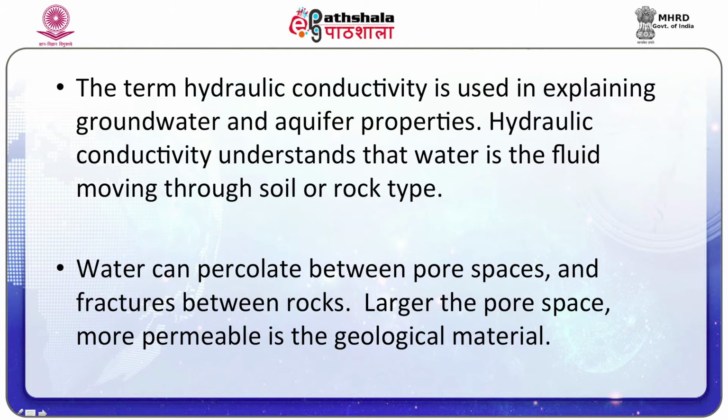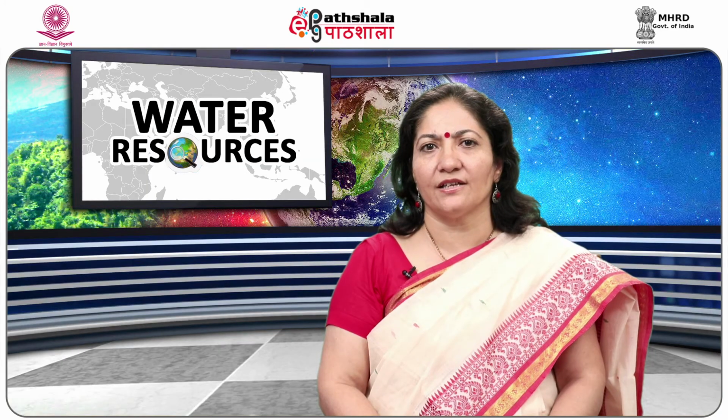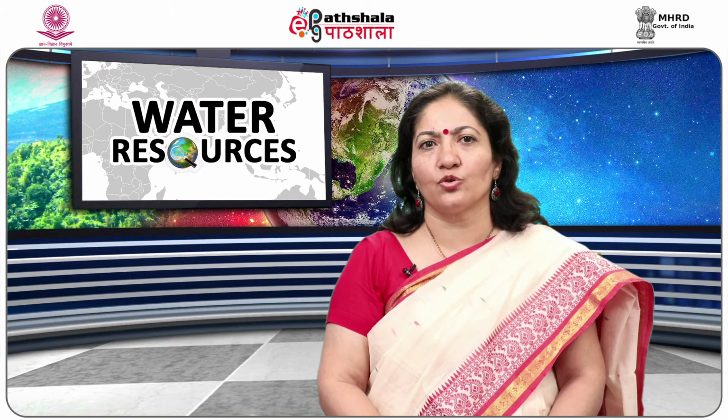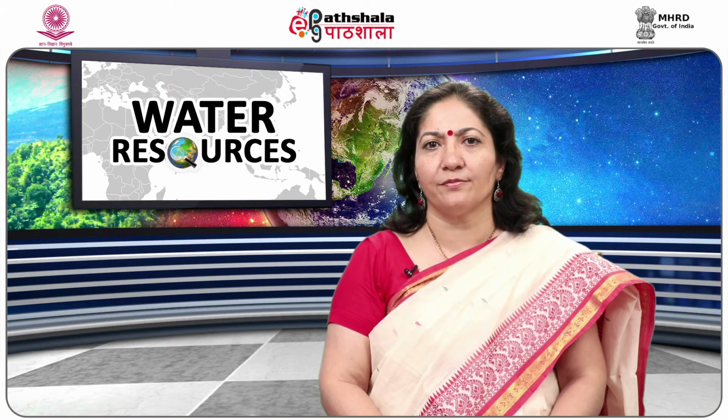Water can percolate between pore spaces and fractures between rocks. The larger the pore space, the more permeable the geological material. A sample of mixed grain sizes, which is poorly sorted, has lower permeability because the smaller grains fill the openings made by the larger grains. Soil, sand and gravel are porous and permeable.